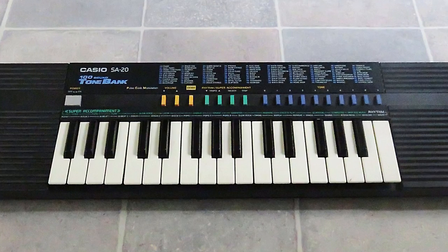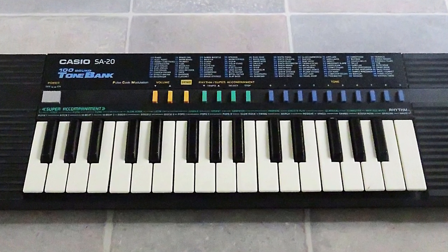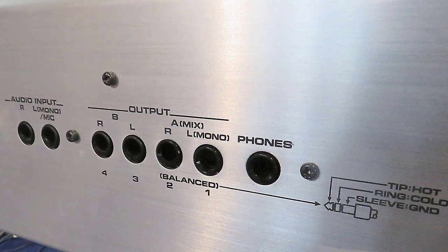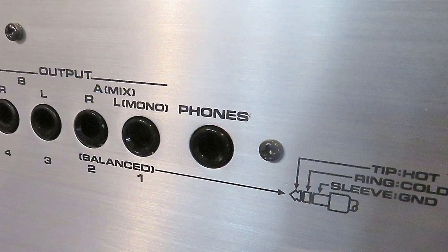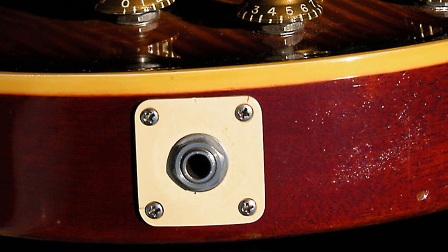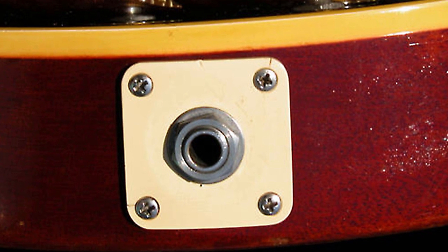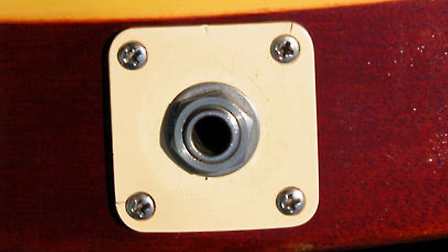Unlike most microphones, most instruments do not have a balanced line output. Some keyboards do, such as shown here. Instead, they usually have one or more unbalanced jack socket outputs. Unbalanced connections are only really suitable for short cable runs, say 3 meters or less. For longer cable runs, we need to convert to a balanced line. This is achieved using a DI box.